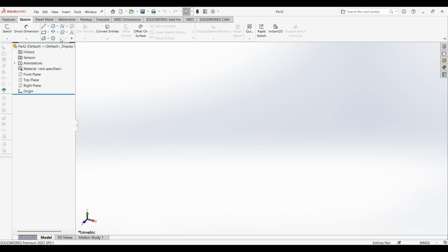First, I will start with the fillet. There are two things basically, one is fillet and another one is chamfer. Fillet means changing your surface into some radius so that the sharp surface doesn't exist in our machine. Sharp surface is a very dangerous thing while doing our machine fabrication, so we'll try to minimize that.